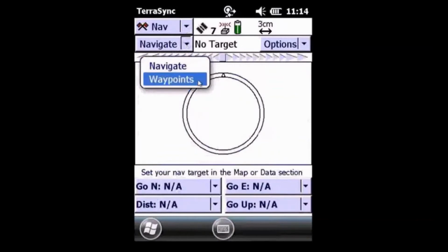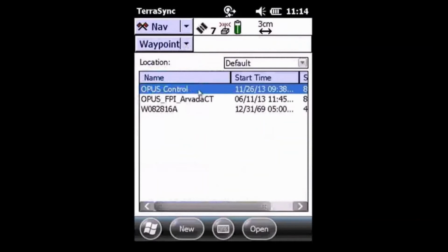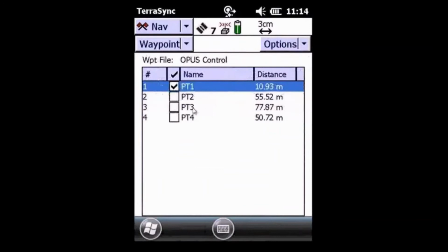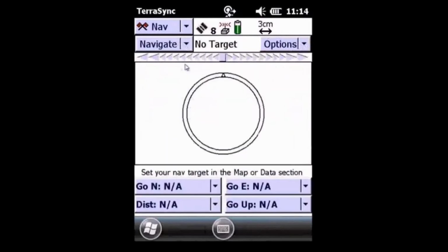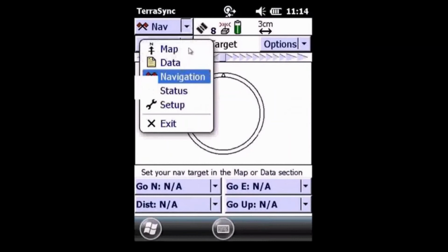So you first need to understand that we're dealing with control points that are operated in NAD83 2011, and we're using a VRS that at this time when this video was created was operating on CORS96. So 2 different systems, okay? Apples and oranges. But if you know how to set things up correctly, these 4 OPUS control points are on NAD83 2011, and what we're going to do is show you that with settings set up correctly, you can navigate to these points.